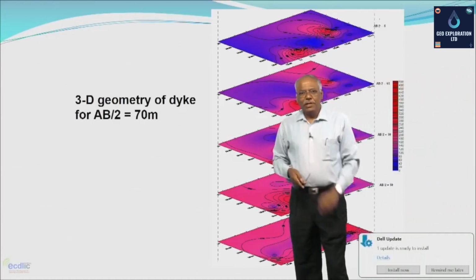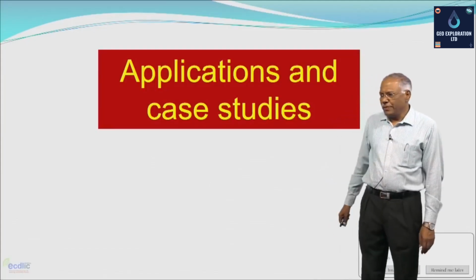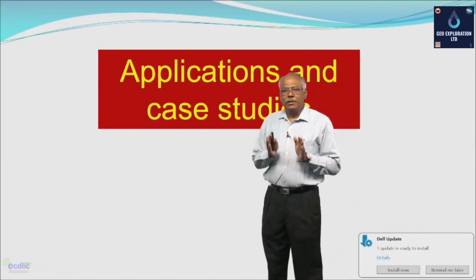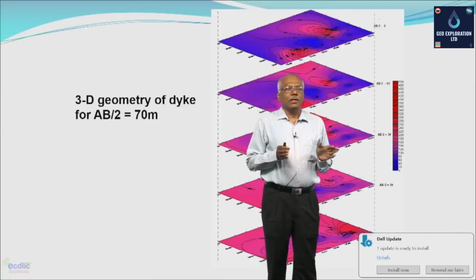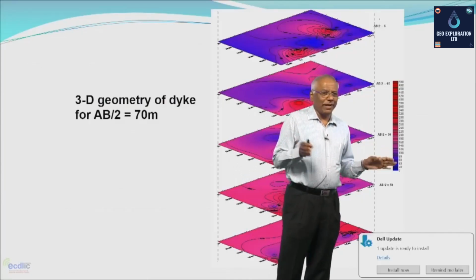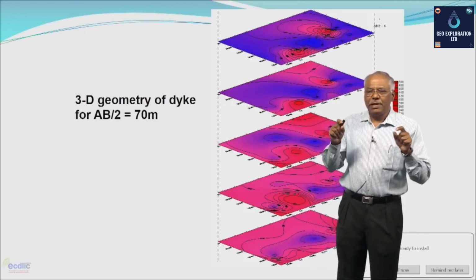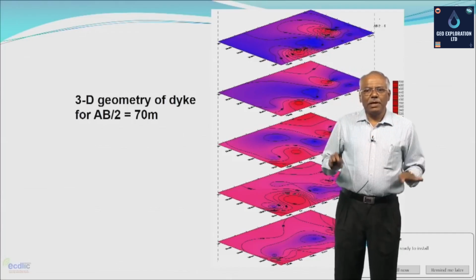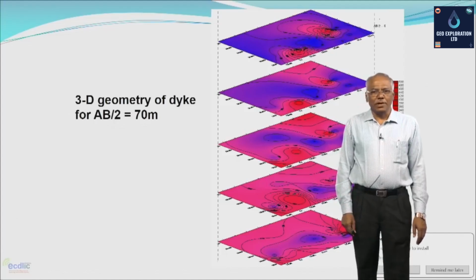It is a very typical scenario that you can gauge with the help of this technique, and therefore, the electrical resistivity technique can give you a fair insight into the occurrence of groundwater and the 2-dimensional and 3-dimensional aquifer geometry of a given area. This is typically how this technique can be used in the search for groundwater.